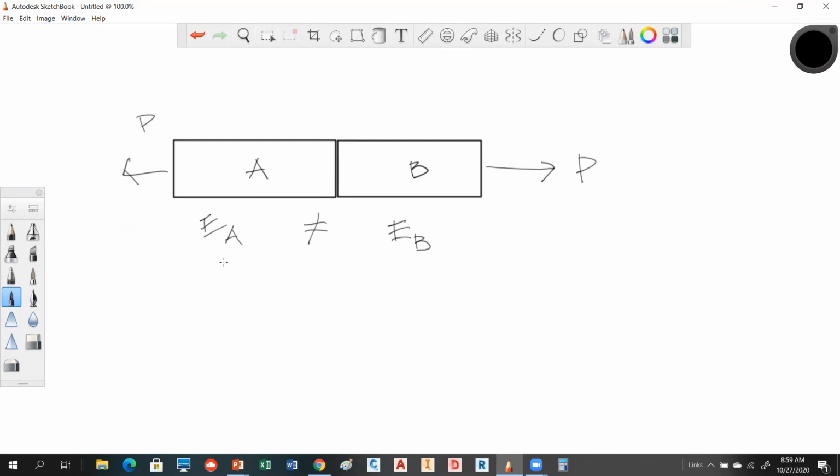And your alpha values, if you're dealing with temperature of those two materials, won't be equal. So because of that, you're going to have other problems that develop. And this is independent of cross-sectional area. You could have the same cross-sectional area and the same length, but it really has to do with the materials themselves specifically. So this is what we call a series problem.